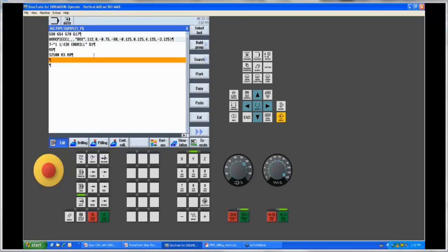Then from there, I'm going to tell it, am I doing inch per minute or inch per rev feeding? We do allow feed per rev in G code as well. You can do a G95, or there's even a unique command if you want to program feed per tooth within the system. But I'm just going to do simple inches per minute, 50 inches per minute. And now we're going to go in and we're going to start creating our contours or our shapes. So just like before, first thing we did was we walked around and profiled out our part. Now what I am going to do initially is I'm going to put an end of program statement, because this is where there's a slight difference from conversational to G code. What you do is you create the shapes the same way.